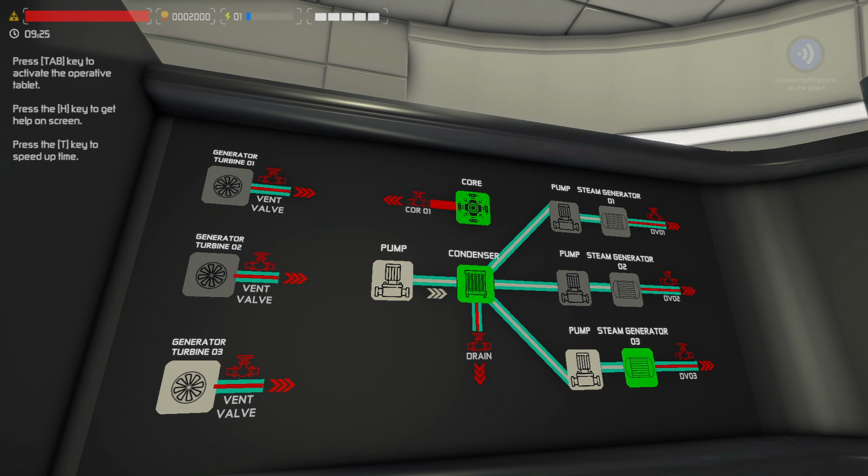Then you also have conduction, and that's between two different surfaces. Mainly that's between the core fuel and the core cladding, and then the core cladding gets the heat removed via the forced convection. So if you have steam, the only thing you have is the conduction through the fuel to the cladding, and there's very little convection that can actually occur. And then the only other form of heat transfer is radiation, where it's based on a large difference of temperature.